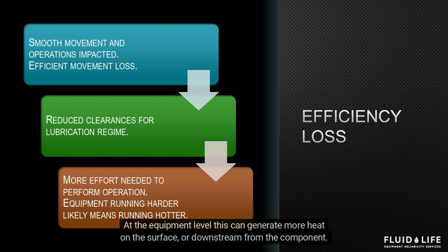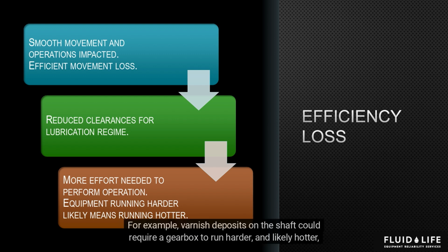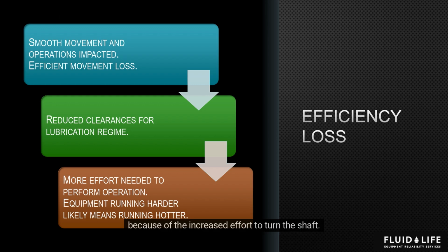At the equipment level, this can generate more heat on the surface or downstream from the component. For example, varnish deposits on the shaft could require a gearbox to run harder and likely hotter because of the increased effort to turn the shaft.